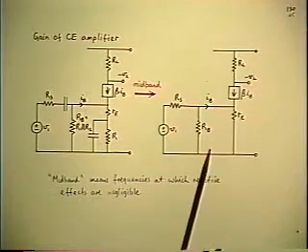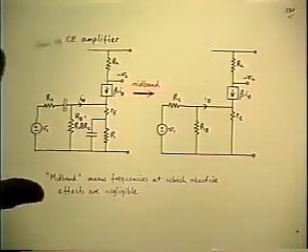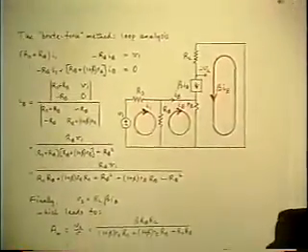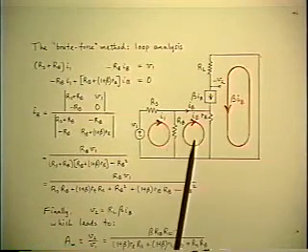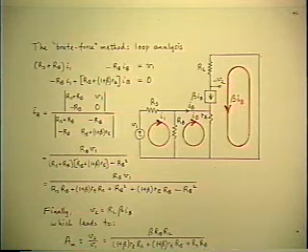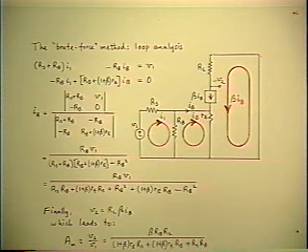So the first thing we do with this AC model now, by the standard approach, which is using Kirchhoff's laws, then we would identify 3 loop currents for that circuit model, which means we would write 3 simultaneous equations representing Kirchhoff's law for each of those current loops.